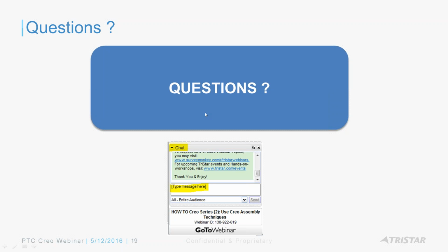So it's just something that you can do starting Creo 2 and Creo 3, wherein you just want to track what changes you did so far when you're working in that particular session. Like I showed you in the example, when you did any type of delete, replace, etc., it's going to give you a list of all the changes you did. So it's really right-clicking on the assembly name and view changes all within Creo.